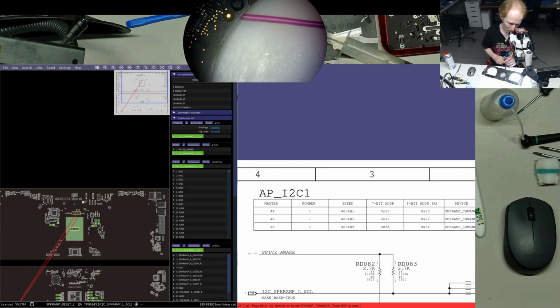So the idea behind this communication protocol is a little bit more difficult, but basically master sends packets. Each packet has its destination. So if someone receives this destination, at some point it should answer by pulling the ACK bit. That's the way the master understands that it was received by someone here.